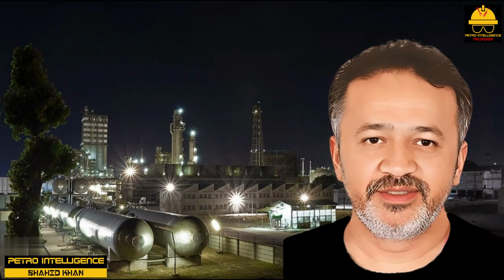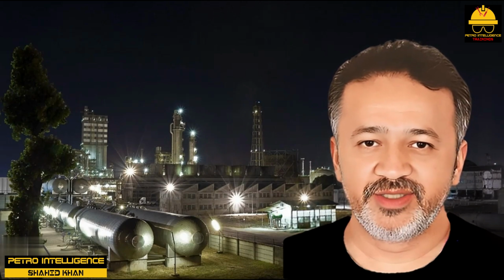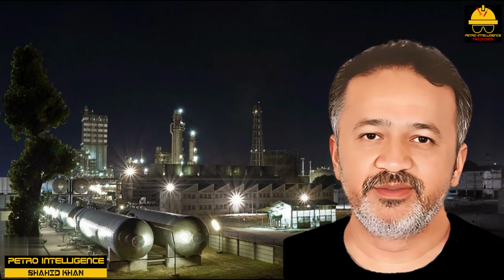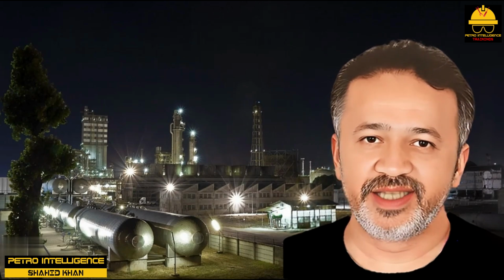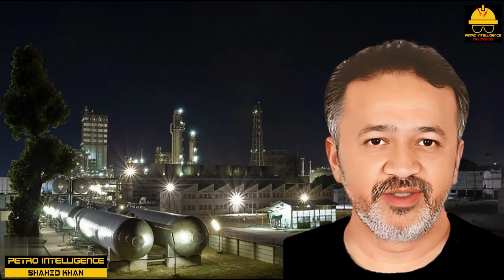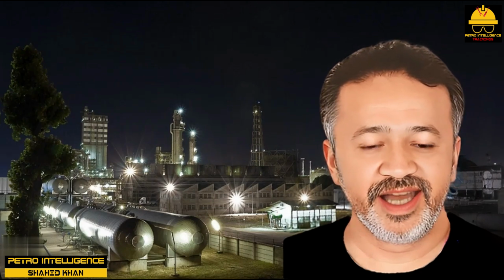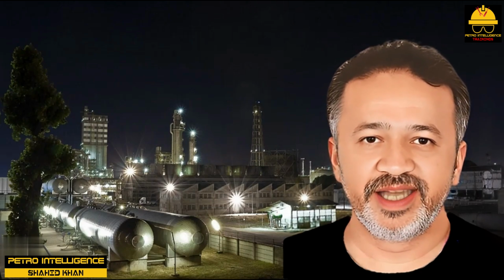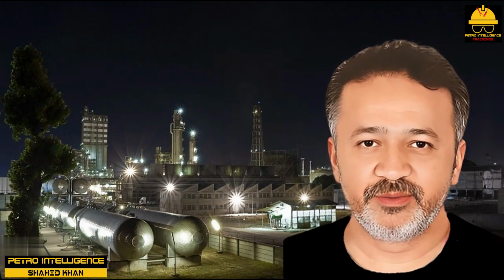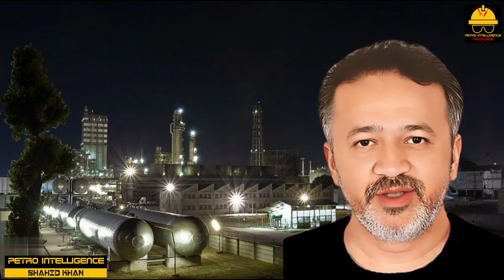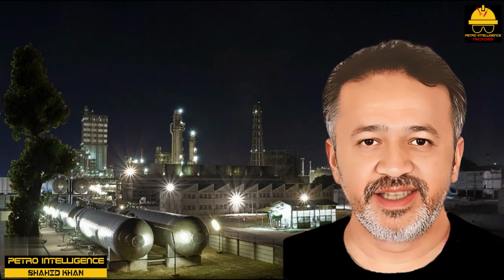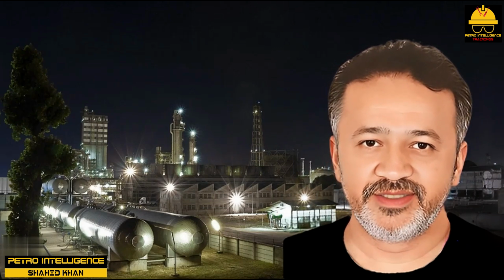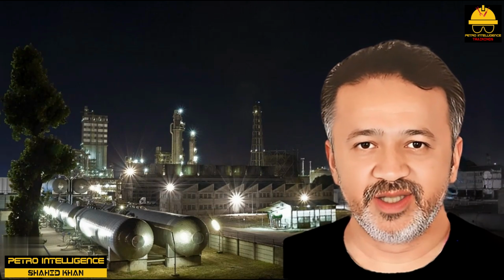Endothermic reactions. Not all reactions are exothermic. Thermal cracking is an endothermic reaction. Heat is absorbed. Good thing, too. If thermal cracking of crude oil was exothermic, all the Earth's crude would by now have turned to coal and natural gas. Delayed cokers, visbreakers, and fluid catalytic cracking units are processes that are primarily endothermic in nature.